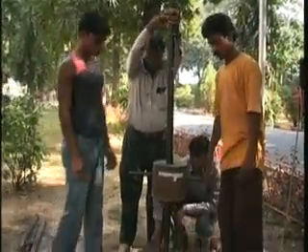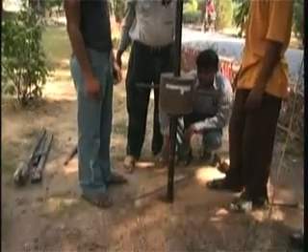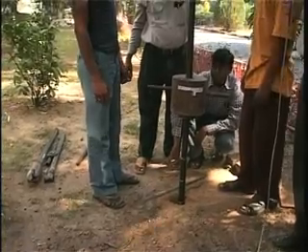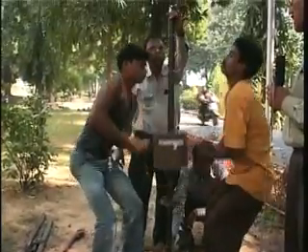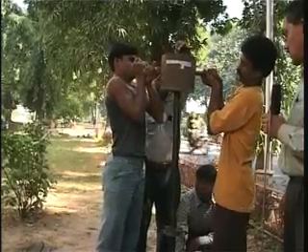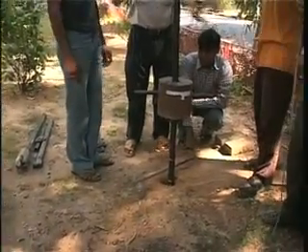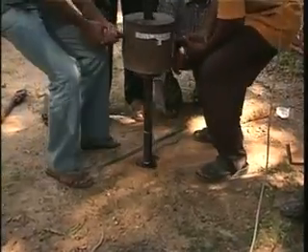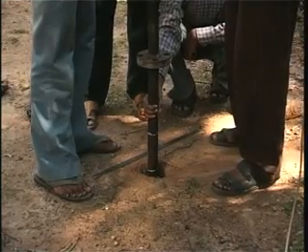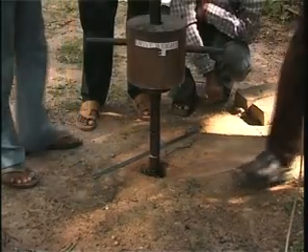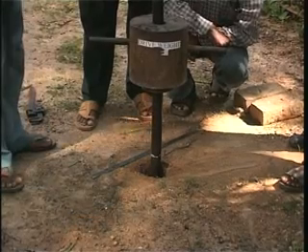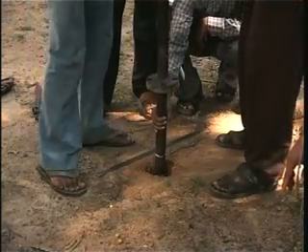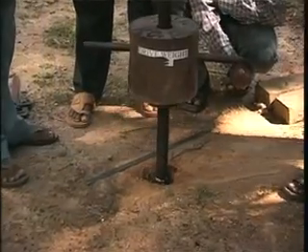Okay, so you see that the first 150 millimeter penetration is completed with only one blow. The soil is quite soft here, and then we are going to go with the next penetration of 150 millimeter. Okay, so that one also basically is penetrated with one blow only. Okay, so this one didn't get penetrated in one blow, so we are going to perhaps need a few more blows. Let's see how many. Okay, so that's it.